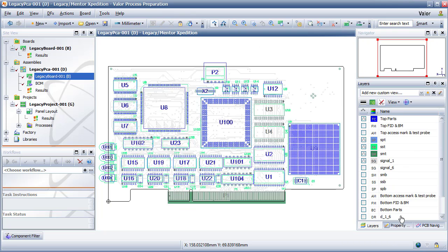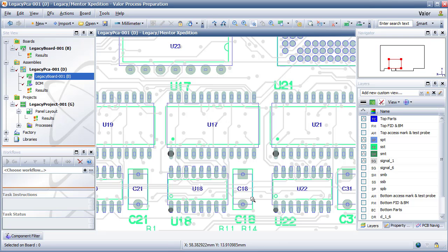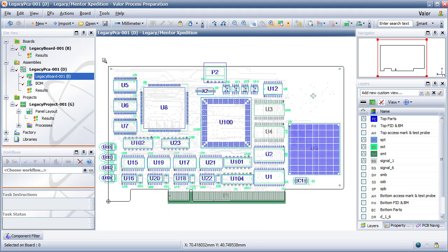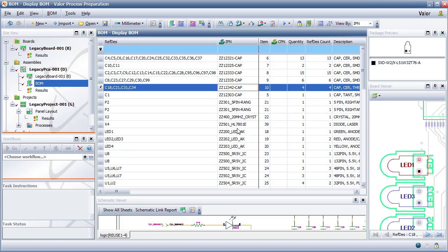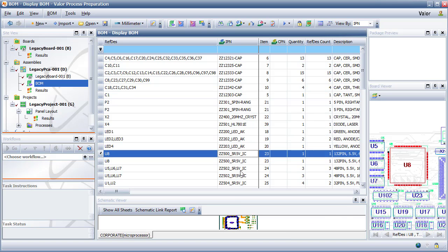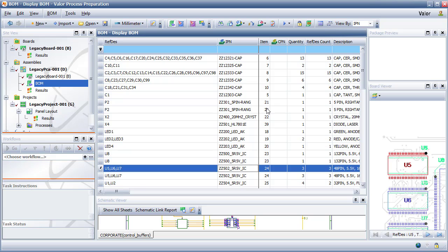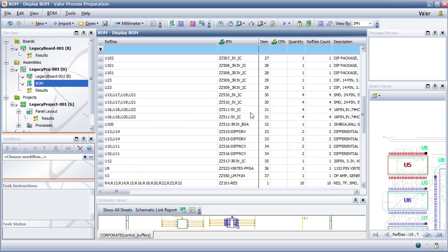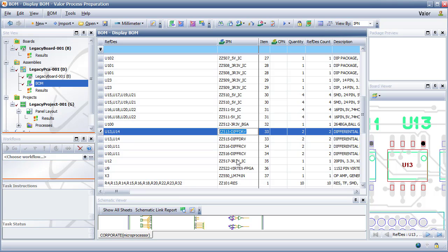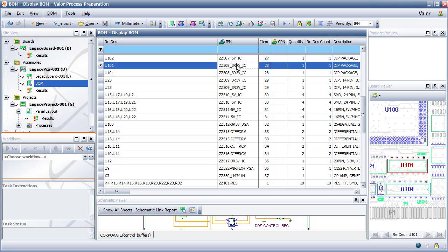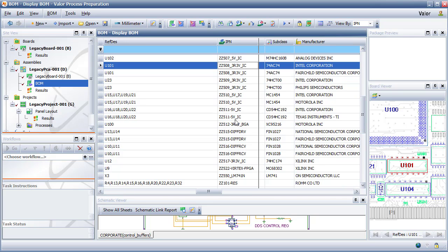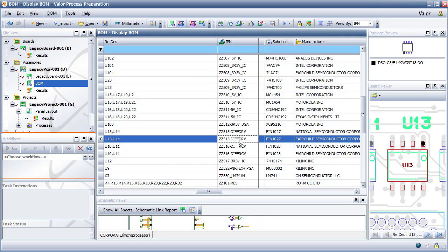Next, we see an assembly, which is a board with a bill of materials file. The BOM describes which part number is placed on which component position, and those that are not placed on a specific variant. The BOM can also specify the manufacturer and manufacturer part numbers for all approved vendors. It is this data that we use to download the Valor Parts Library, or VPL, data from the cloud. VPL gives us exact geometrical shape data, including height, for each part on the board, including alternates.